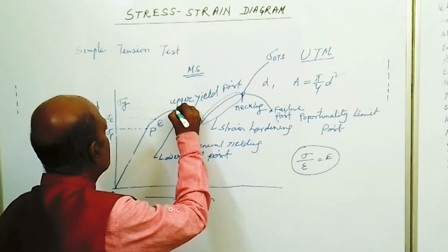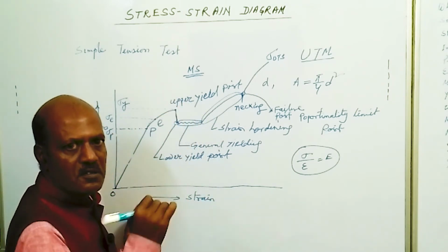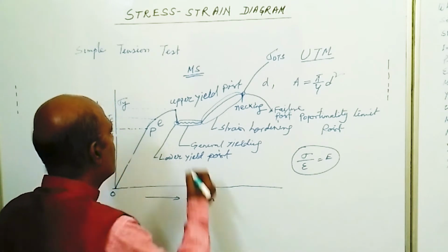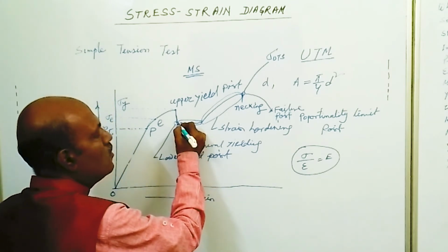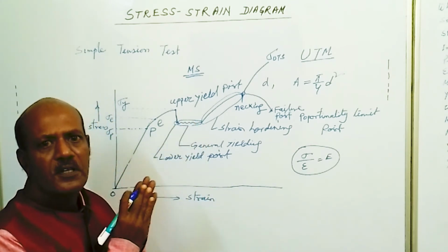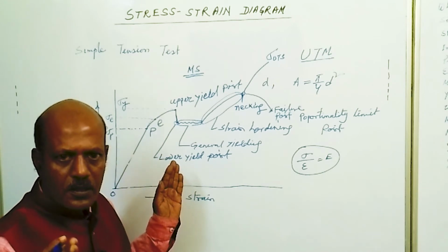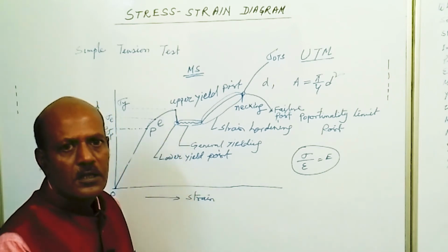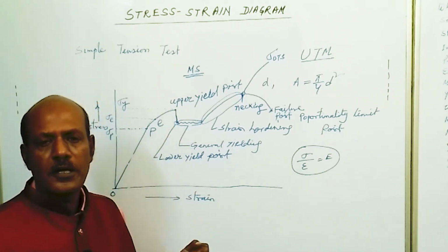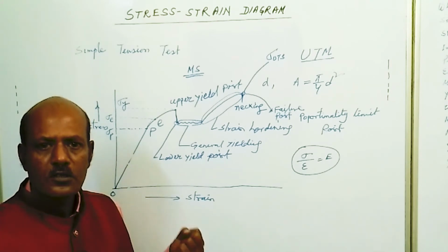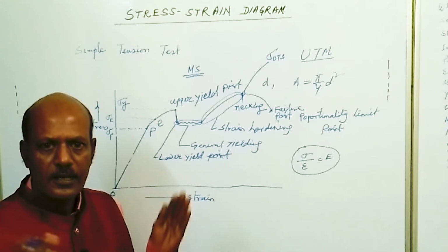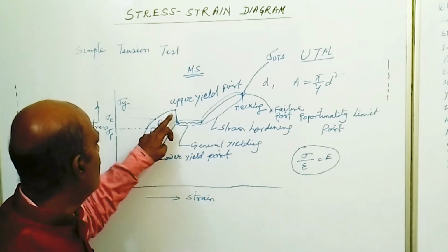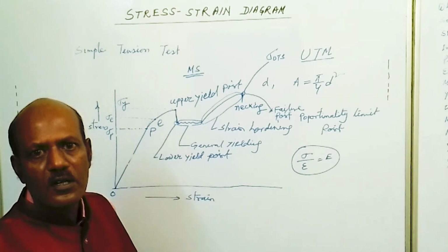So if we cross this sigma y value, it is seen that at a lower stress value there will be appreciable deformation in the body. This is because in every solid body there are thousands of defects. The defects start moving as soon as this upper bound condition is exceeded.